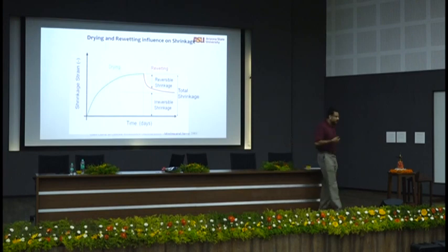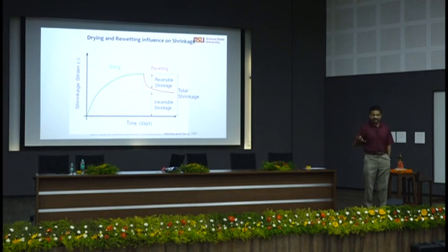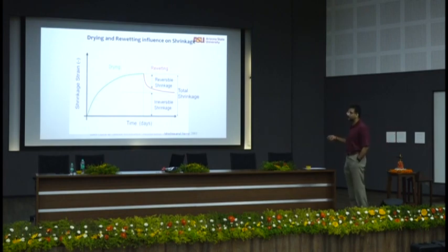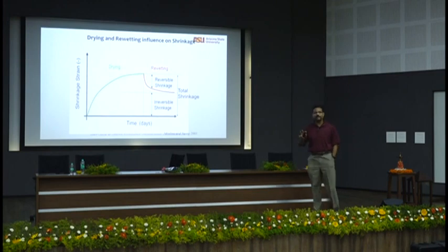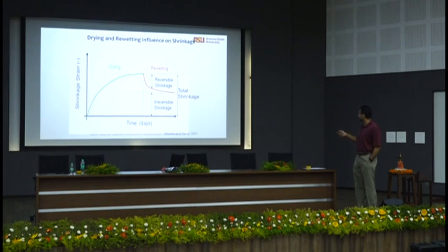Now, if water loss is what is causing cracking, once I see the crack, can I go pour a lot of water on concrete and reverse cracking? Kind of, right? It's not completely true. There is a little amount of reversible shrinkage. I'll try to get into the theory of this. It might be a little more complicated than you want, but I'll try to explain that. There is some shrinkage that is reversible and a lot of shrinkage that is irreversible.